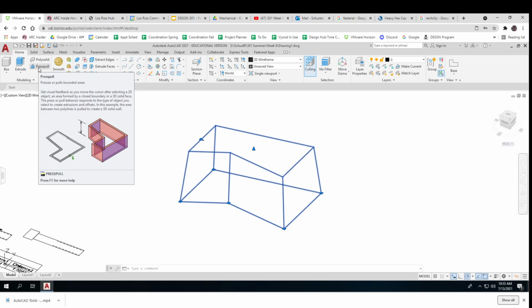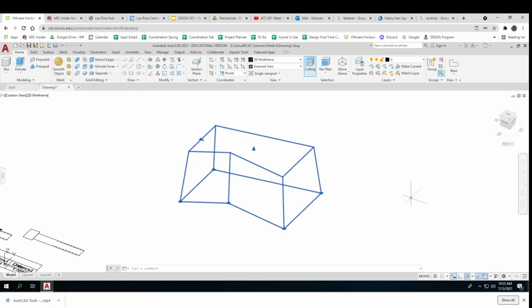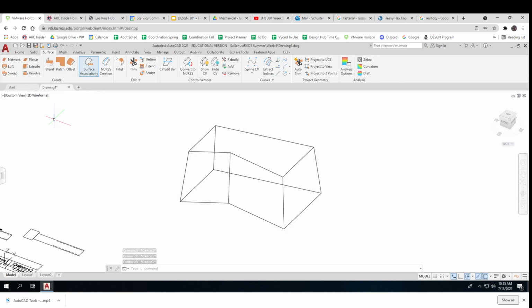And so we used to have to make regions and do this and do that. It was like a lot. Yeah, because I did the floating arm, and I played around with the extrude for probably an hour and a half before I gave up, and then I did the entire thing in press pull in 5 minutes. Yeah, press pull is, unless you know about that region command.